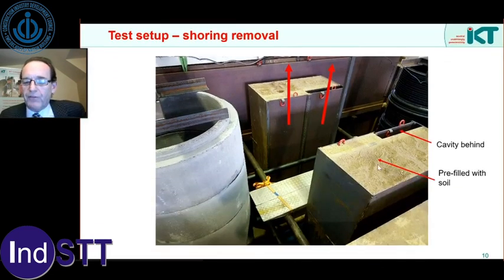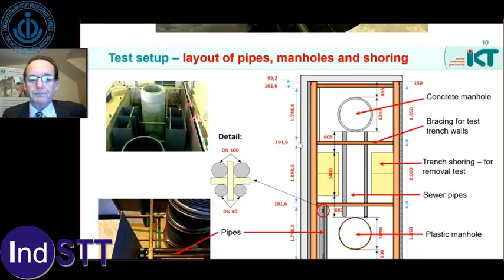So what we created was these boxes either side, simulating a narrow trench with shoring that could be removed. We filled them with sand right up to behind the shoring in 2 cases, but we left a void in the others, as you might find in an uneven trench. We wanted to see what would happen when the flowable backfill moved into those voids when we removed the shoring.